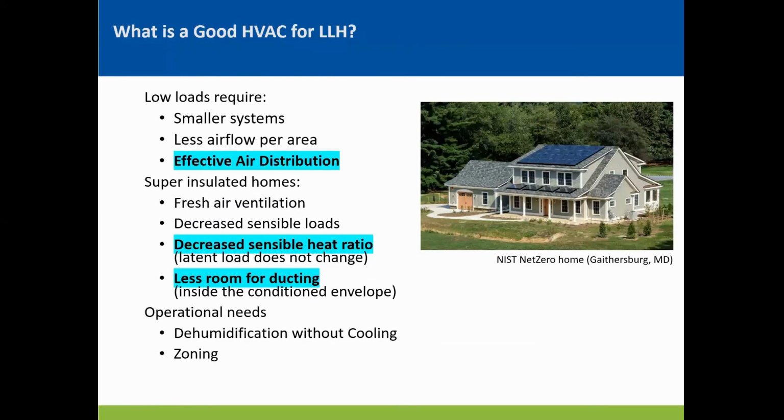So what's a good system for a low load home? What's different? What do you really have to pay attention to? Well, let's start with the loads. They are much smaller. They're extremely small. So that means you have smaller sized equipment, and smaller sized equipment means you have a lot less airflow. So therefore, effective air distribution is very, very important.